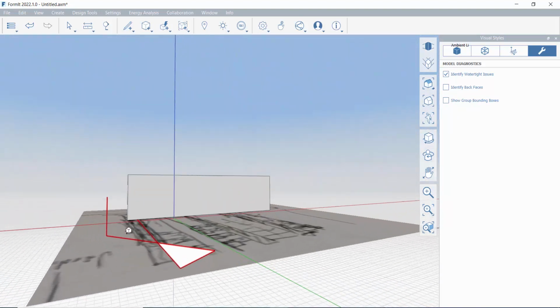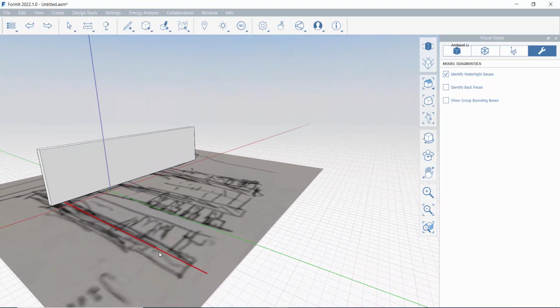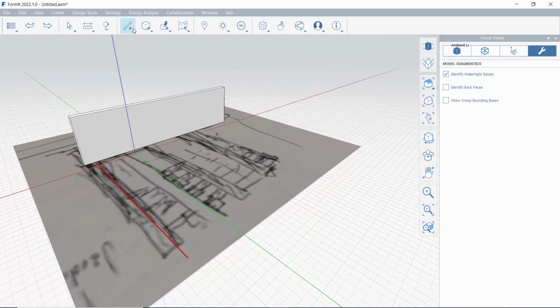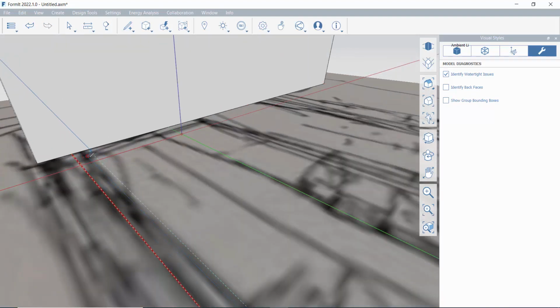Right? I can be drawing all sorts of weird ways, which is why you really need to pay attention to working on your orthogonals, okay? So what I'm going to do this time, I'm going to make sure I'm on that red axis, the x-axis. Okay, I'm going to come over 2 feet again. I'm going to come all the way back to this wall along my green axis, which is the y. And also, as I'm working that direction, if I hold down shift, it's going to bold that line. Okay, when I do that, no matter where I move my mouse, it is going to lock me to the y-axis. Super, super important feature. Okay, so I'm going to close that off.